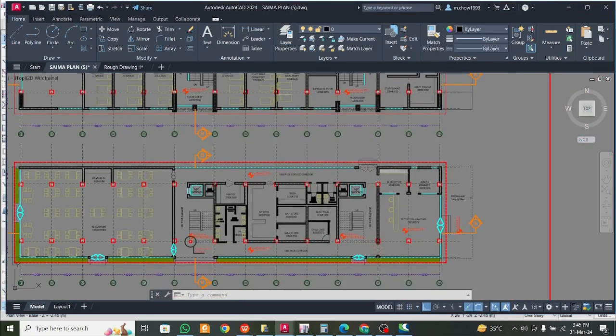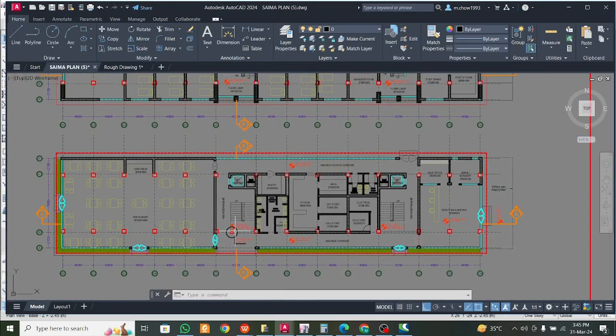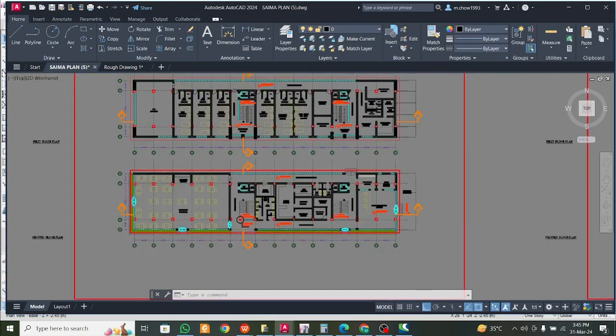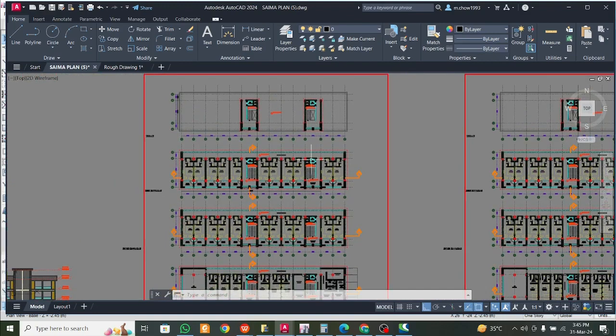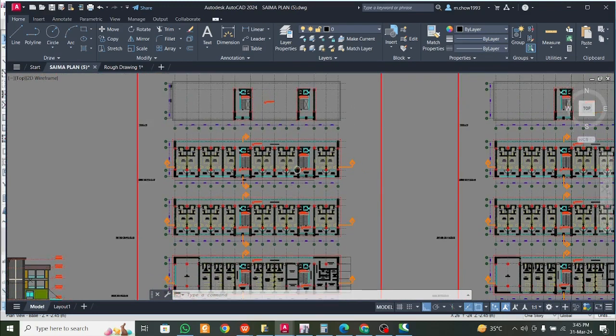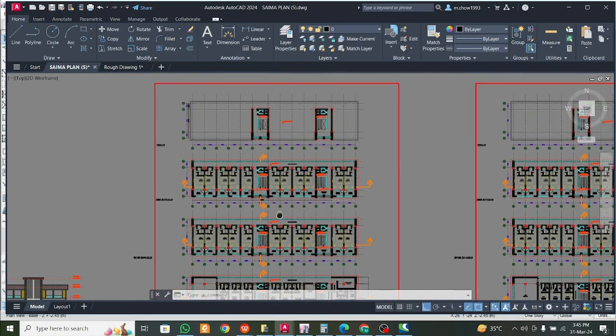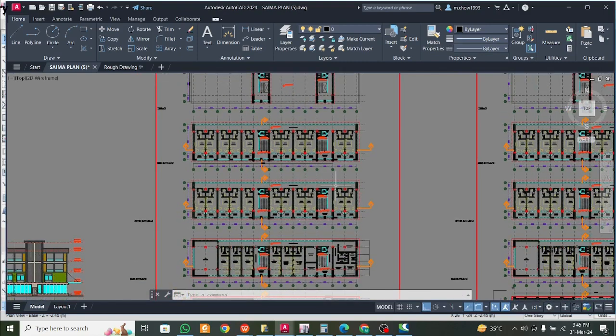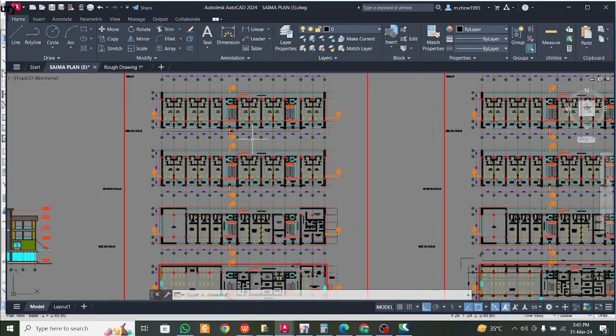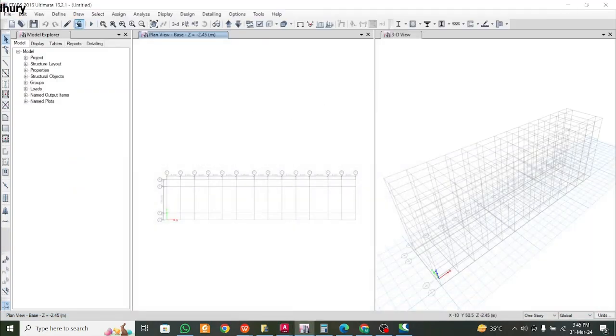Since in this particular level I'm not providing the grade slab or the RCC slab, we're directly giving a PCC over the plinth level, so we'll consider diaphragm in 3. You can also consider diaphragm in the headroom level as well, okay, but we're not using it for the wind load analysis. So we're using diaphragm for these 3 levels. We'll create 3 diaphragms now, okay.